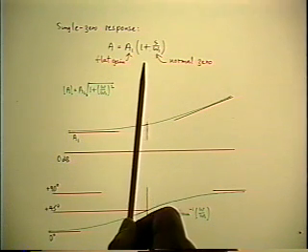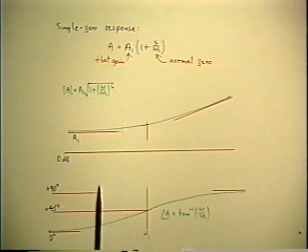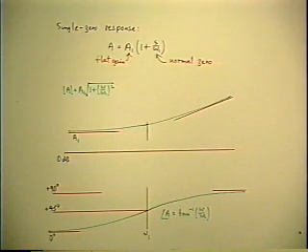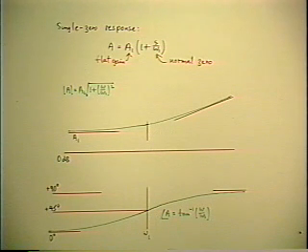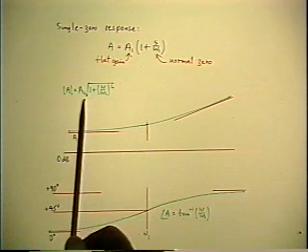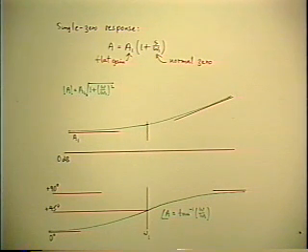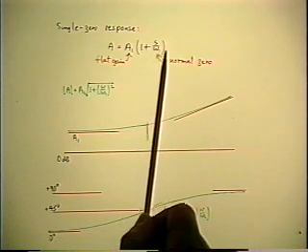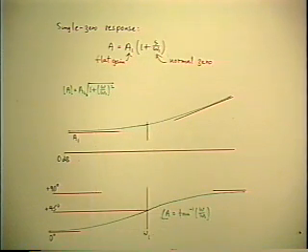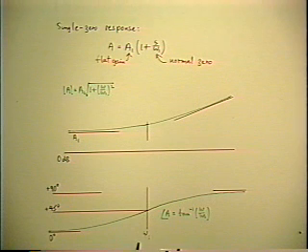Because moving a function from the denominator to the numerator on a logarithmic scale is the same as reversing its sign, which is turning it upside down. Now you see that the same thing applies to the phase graph, because the phase function for a zero is simply plus the arctangent of omega over omega 1. So it's simply the reversed sign from what it was for the pole, which is a vertical inversion of the phase graph, because that was already on a linear scale.